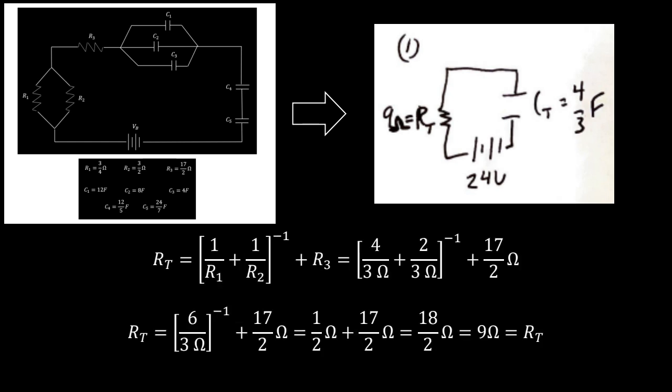If we're going to simplify the resistances, well, we know that R1, R2, they're each just one resistor on parallel paths. So their equivalent resistance would be 1 over R1 plus 1 over R2 raised to the negative first power. And whatever that value becomes, that would be an equivalent resistor in series with R3. So we can just add that to R3.